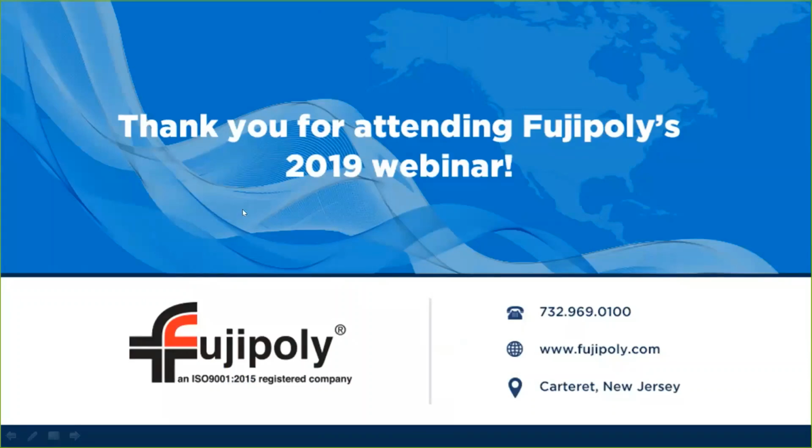Okay, so we'll go ahead and begin answering some of your questions here. I see more of them are coming in, so we'll try to grab those as we move along. One of the ones I'm looking at here: can you dispense these types of putties? No. The putties that we discussed, the PG25A, GRPM, PG80A, are specifically in sheet form so they can be easily handled. Our dispensable product line consists of our SPG type materials, which are silicone gels, and those are dispensable. So these putties are in sheet form and they're intended for ease of handling manually.